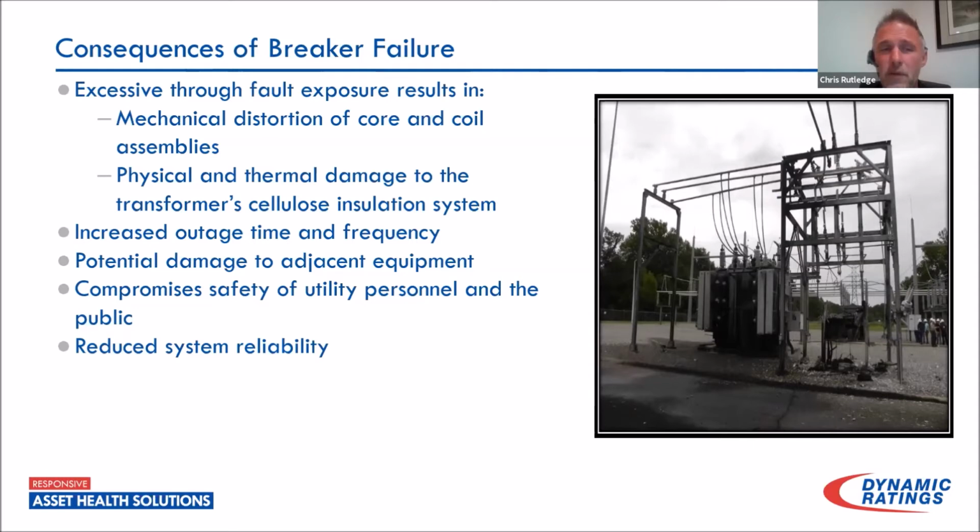A lot of times, neither one of these will be able to be detected with your offline testing until their latter stages. I've had instances where transformers took a fault and tested well. Had a low side bushing failure where, after the failure, we ran a power factor test. Power factor looked good. We had almost no change in capacitance. Because the failure was so close to the core and coil assembly, I asked for an internal inspection to be done, at which point we found that the blocking of the transformer had shifted about an inch off the line. All of the bracing had been shattered, holding our leads together.